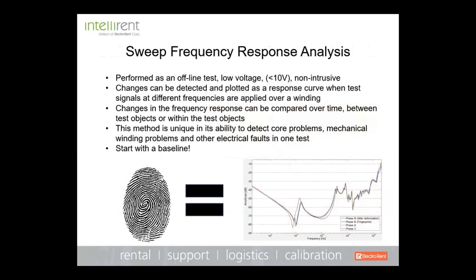And basically what we're doing is SFRA, and in case you're not familiar with it, is an offline low voltage test, and non-destructive, of course, where we're actually going to do a frequency sweep and record the decibels and plot this out, both three-phase and single phase. This type of test has been around a long time, and it's kind of like having a fingerprint. And this is why having a baseline is so important.